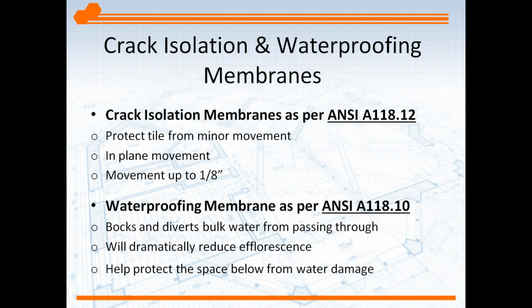They'll reduce efflorescence, and the way they do that is they don't allow the bulk water to pass through the tile installation into the substrate, and then as it dries, for that to pass back up through the flooring in vapor. It'll pull all the efflorescence from that concrete back up through the tile, through the grout, and a waterproof membrane doesn't allow that because it doesn't allow the water, the bulk water, to get to the concrete in the first place. It'll obviously help protect the space below in a bathroom area.